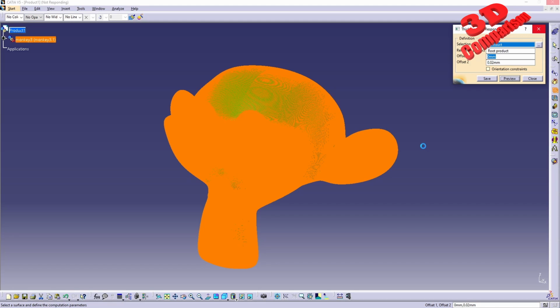So this is why I prefer to add Blender to the CATIA V5 reverse engineering workflow, because the processing capabilities, as we can see, are not that great. It works fine on small meshes, but when you are actually dealing with 3D scan models, you will not have small 3D models, only if you're gonna decimate those and try to convert them afterwards, but that will also remove a lot of the details from the model.